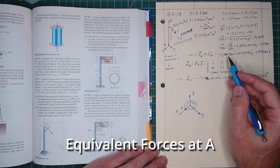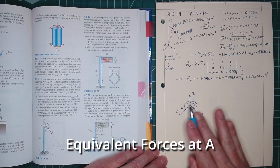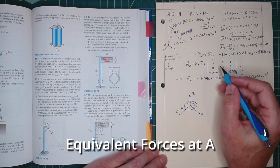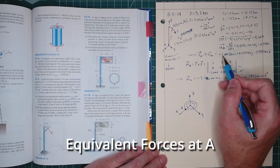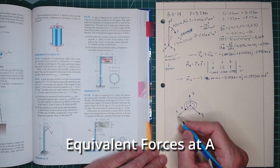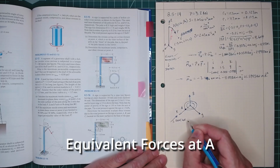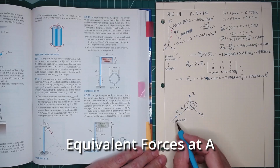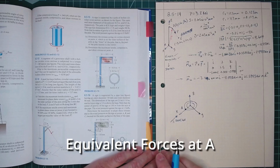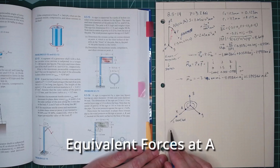But basically, these forces are going to be really acting about this point across this entire cross section here. So let's take a look at what this force means. In the I direction, we have a minus 1.0662 kilonewtons. So really, in this direction we have 1.0662 kilonewtons. I've drawn it in the negative x direction. I've gotten rid of the negative sign, but it's pointing in that direction. So we need to be careful with the directions of the arrows that I'm going to be drawing on here.